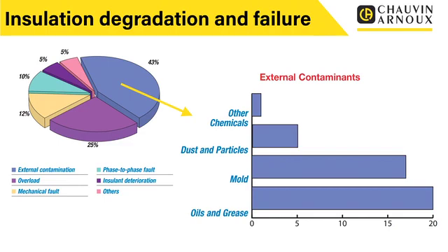So when we're carrying out insulation resistance testing, this is just a way of non-destructively checking the condition of the insulation. But again, we're only measuring this thing. An insulation resistance test isn't going to stop these things from happening. What's going to protect your insulation and ensure fewer failures is minimizing these factors that we've just looked at on these previous two slides. So insulation resistance testing is a method of checking the condition of the insulation over time. But if we do identify insulation resistance problems, one, it may be too late. But two, we actually need to look at the root causes, which again are these things that we've talked about on these slides.